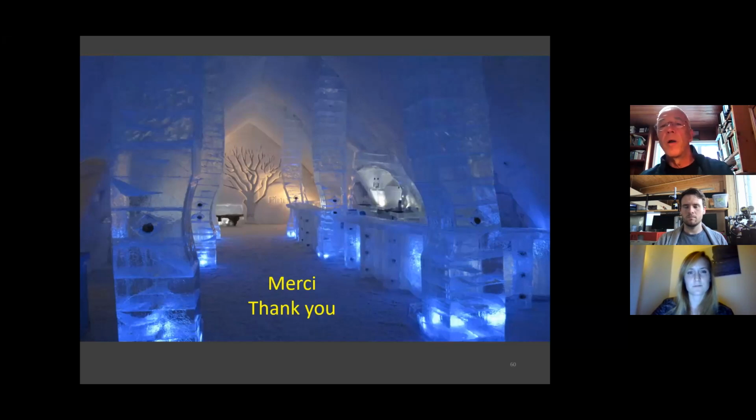I've shown an example where if you had a 7 meter thick embankment on ice-rich soil with temperature of -0.5, you'd get probably somewhere around 80 centimeter to 1 meter of settlement over the design life of the structure. Well, that can perhaps be managed. So if you have a gravel road, every 10 years you can go fill a little bit, fix the dip, and it will continue. But you can manage that. If you have an airstrip, you cannot tolerate that kind of settlement, especially if you have a paved structure where it's not very easy to come and remove the asphalt, fix the level, and then repave on top. That's very expensive. And again, an airstrip, you cannot allow a dip in the middle of an airstrip. So it depends on your tolerance.